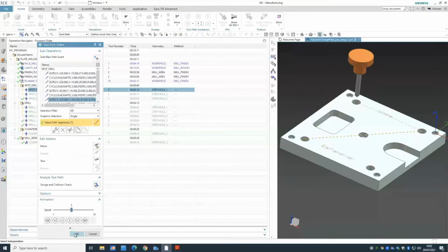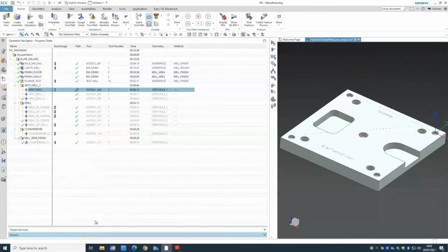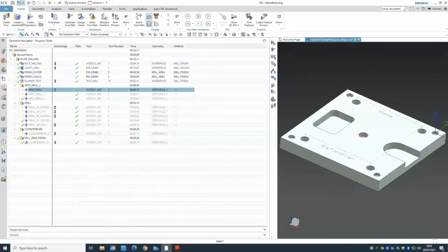But I don't recommend this one because there's a better way of doing it. If I do that, let's do it for you. And you can see it says skip the rest because you have to modify everything and you're not going to do that. You don't want to waste your time. So let me make sure I undo it. One of the best ways from the top, make sure you are in the Operation Navigator. Operation Navigator.